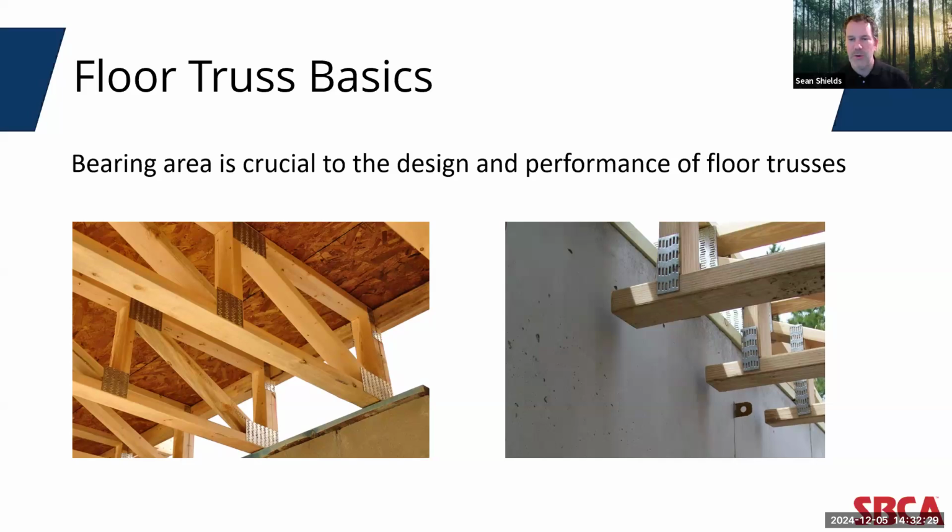A larger bearing area spreads the load from the truss more evenly across the supporting members, reducing stress at the contact point and minimizing the risk of crushing. And we'll see a few details here that seek to do that. The key here is that the truss designer must carefully calculate the required bearing area based on the anticipated loads on the truss and the strength of the supporting wall material. Even the grade and species of the wood used for the bearing surface, both of the truss and the supporting structure, impacts a floor truss's capability and capacity to handle compressive forces. And for these reasons, most of the details that we're going to focus on with the different walls, rough openings, and floor truss configurations should be designed and installed to maximize available bearing area. So with that in mind, let's take a look at the system's details.